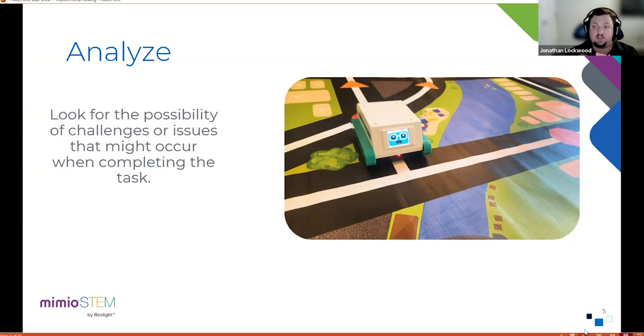So these are things like understanding how the sensors on the robot work, right? As you're learning how to use the MyBot, you have to have an understanding of what these sensors do and how they operate. So looking at using a color sensor to do line following, we would start out with a very simple foundational process where students are just learning how the sensor reads in data and learning how we can take that data and then create some sort of logic that keeps that data from the sensor within a certain constraint that would allow it to stay